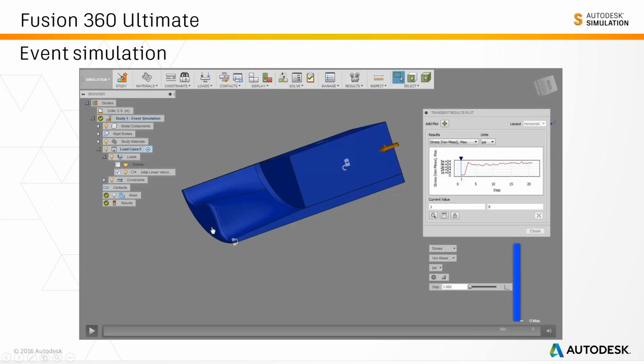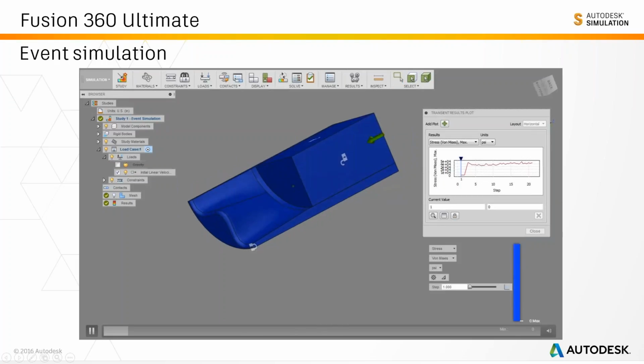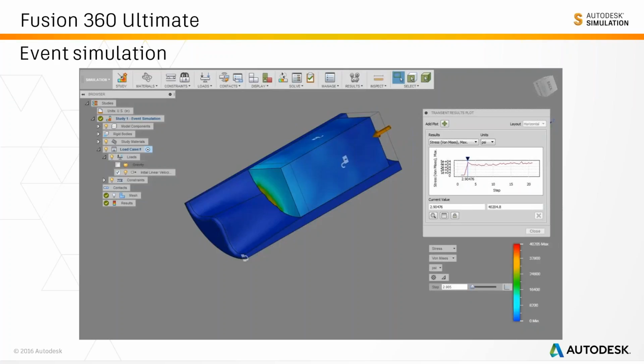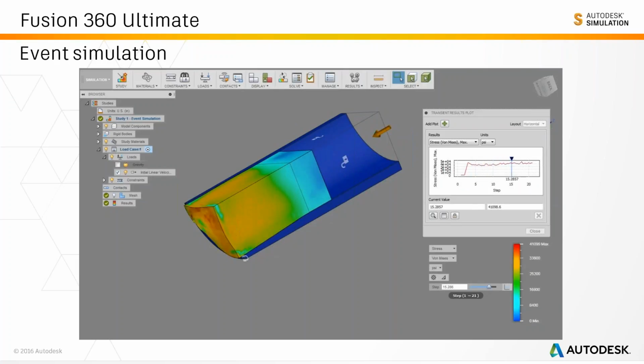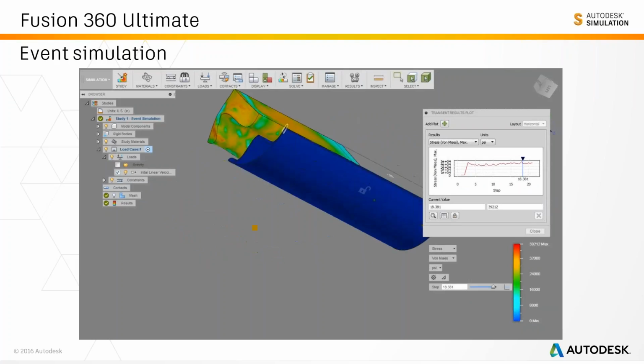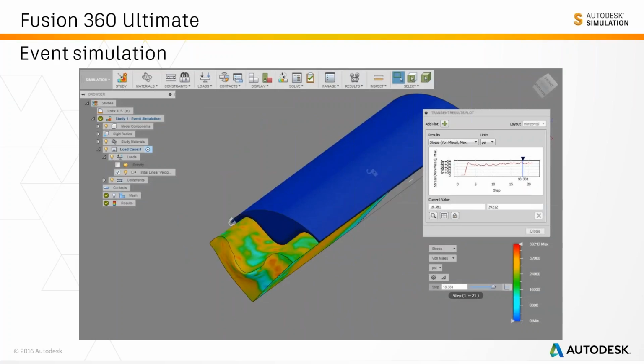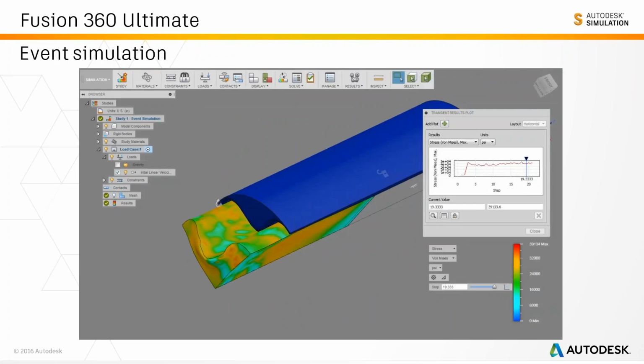where, let's say, a copper billet is drawn through a die. The die is defined as a rigid body, so infinitely stiff, and by specifying a certain prescribed velocity on the copper billet, we're getting to look at the variation of stresses, and you can see how the maximum stress is around the yield value there once the material goes plastic, and the final result, the final shape of the component.